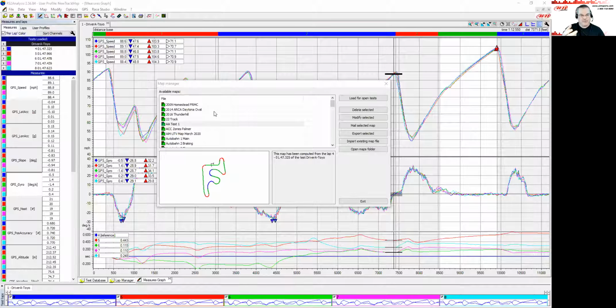So when I build a track map, I give it something specific. This is a map just for braking segments, right? So I end up generating a track map just into the braking and ending it just before I start to trail brake, and then I end up with split reports with just braking data. Or I have one that's just acceleration zones, or one that's more driver related where we drive through segments. But you need to name those all slightly different.